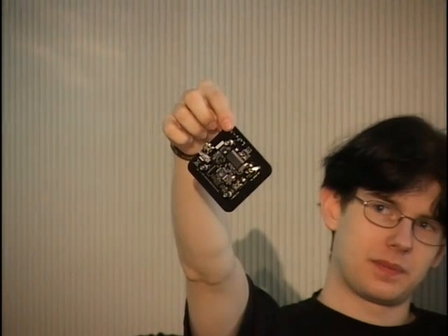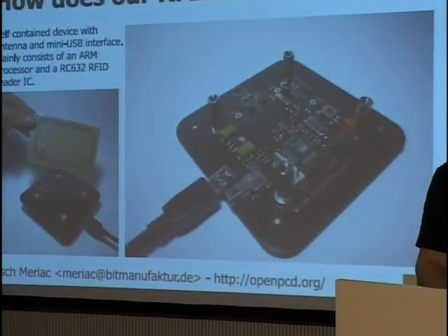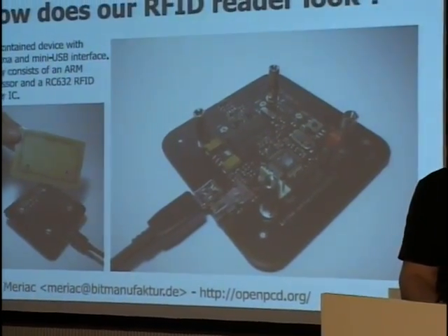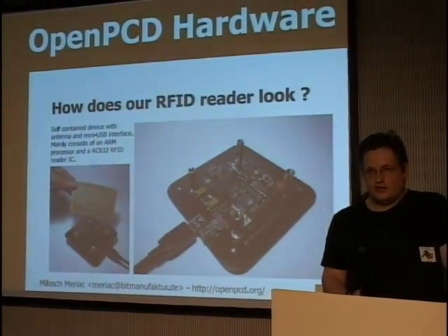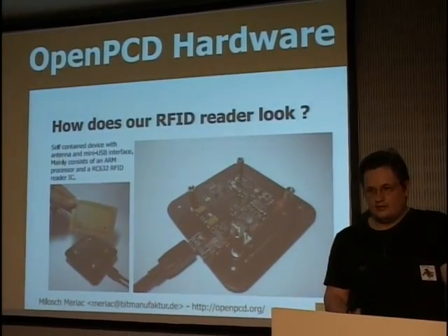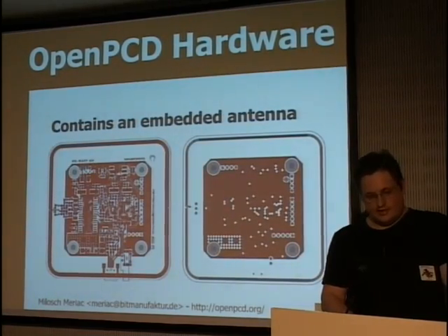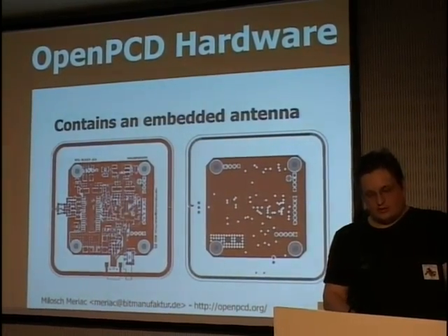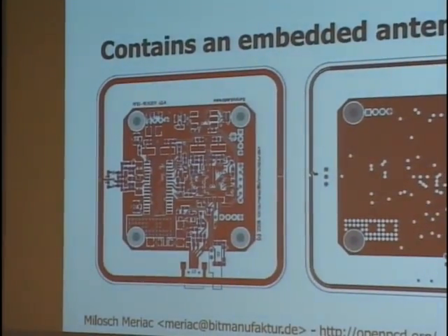The trace you see running around the top and bottom layer on the picture is not the antenna itself. It's just a shield to remove the electrical component of the field and only use the magnetic component. The real antenna traces run inside the second and third layer, and you can see how the internal structure looks like on this slide. The red one is the top layer.